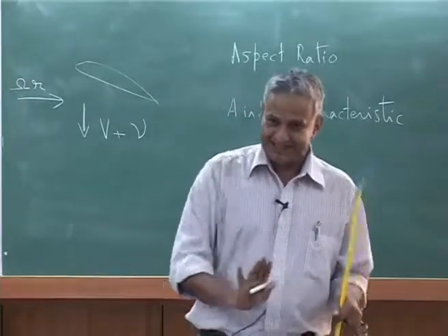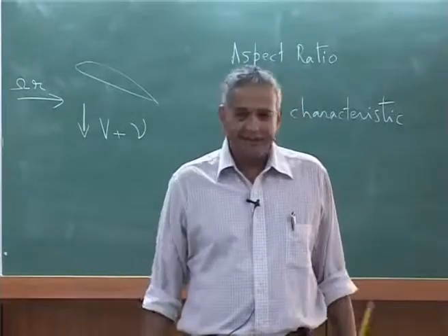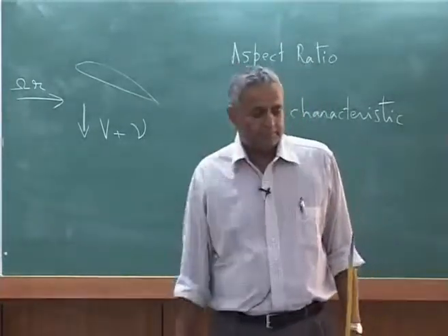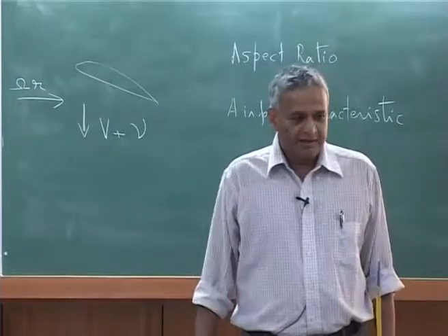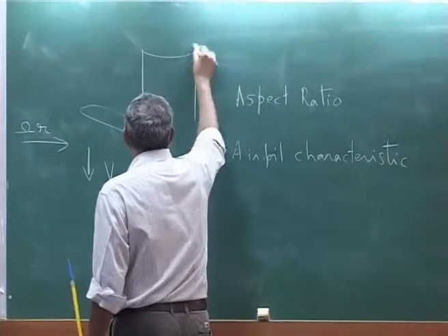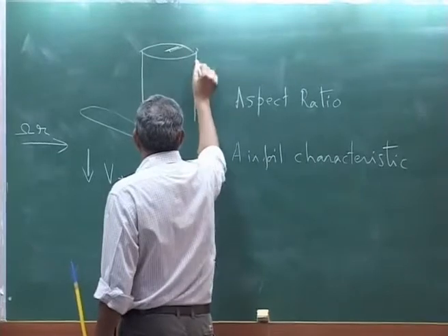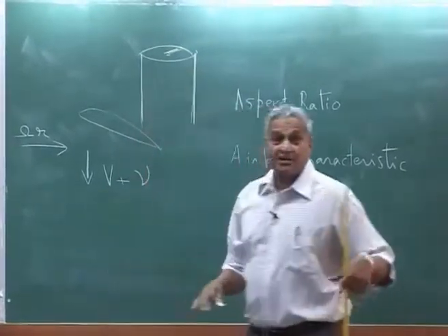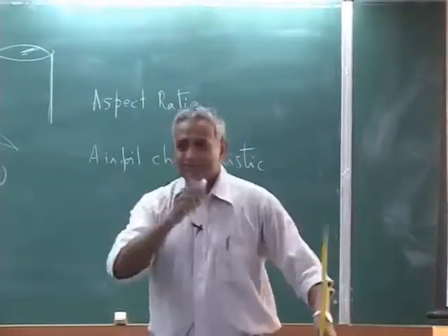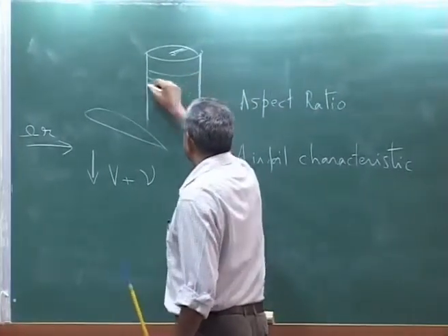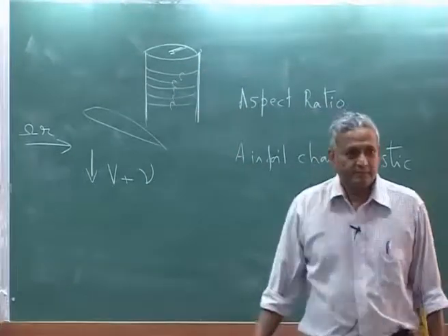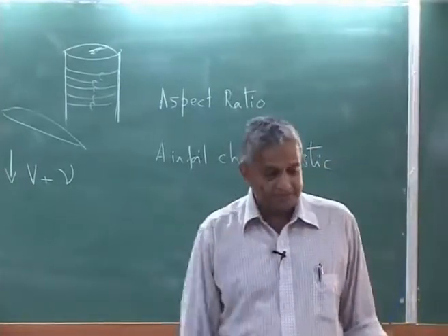Today I am telling you vortex theory is there, it is used, but the beauty is, if I consider a hovering rotor and then you assume that the vortex is in a cylinder, and it is an infinite number of blades, an actuator disc, that means it is just a lot of circular continuous vortices. It is easy for integration, that was what was done earlier.